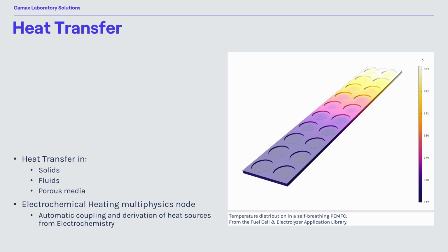So now we also had heat transfer. Now we can go further, so we can extend the model into the fluid calculations. So we can go back to the fuel cell module, and where is it? Fuel cell, thermal management, non-isothermal. And as soon as it's opened, we can investigate the different setups there.